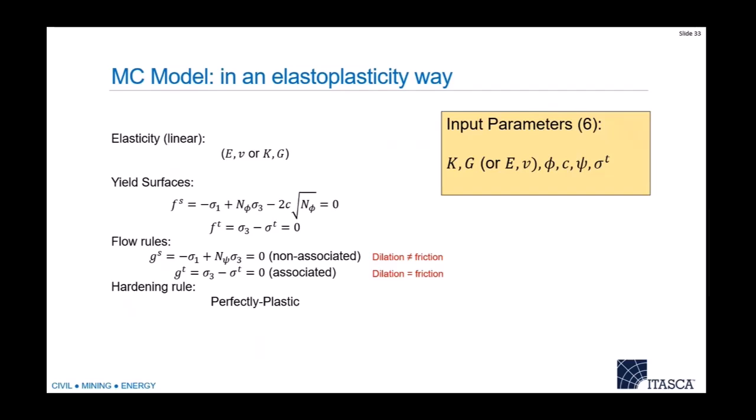The only reason I'm bringing this up is that there are some analytical solutions for some problems where they assume that the dilation angle is equal to the friction angle, which makes the math easier. So these guys can work out the answer to these problems by hand using math and not using models, if they assume that the dilation angle equals the friction angle. We're actually going to do that example a little bit later. In reality, nobody ever does that because that's stupid. The only reason I'm bringing it up is because we're going to show an example later where they have an exact solution that somebody worked out with math. Anyway, there you go.